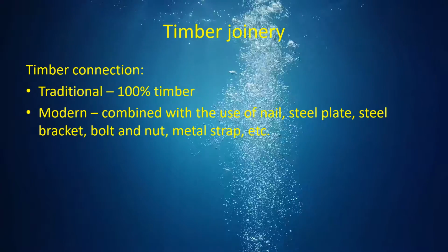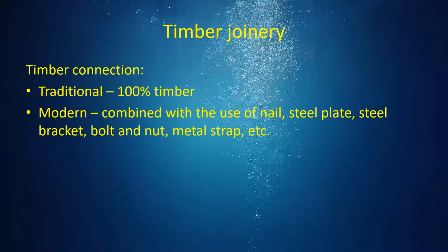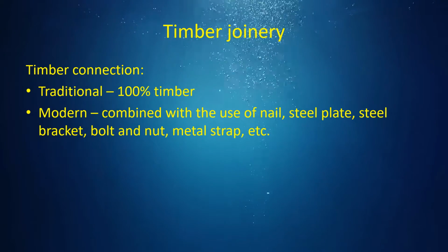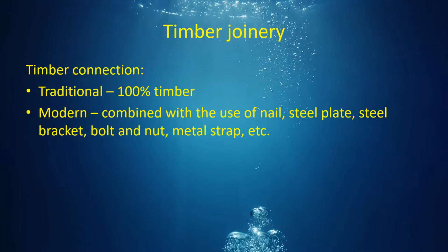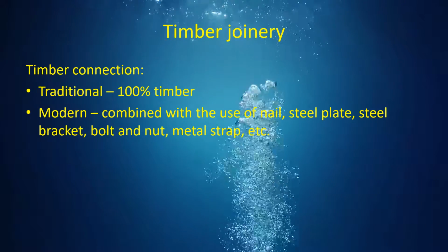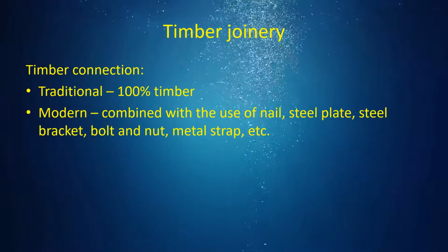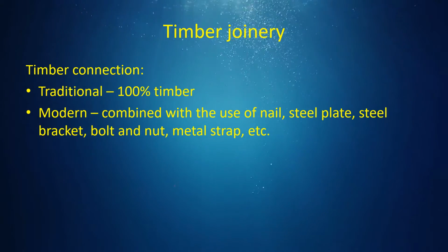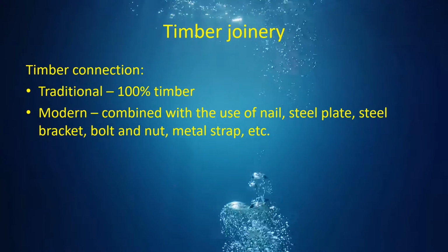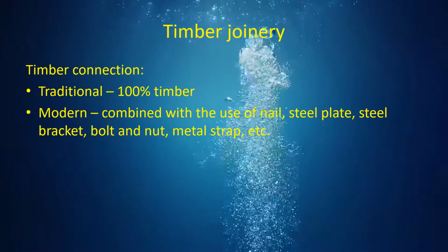There are many types of timber connection methods. Number one, traditional method, which uses 100% timber joinery. Number two, modern method, which uses a combination of nails, steel plate, steel bracket, bolt and nut, metal strap, and so on.